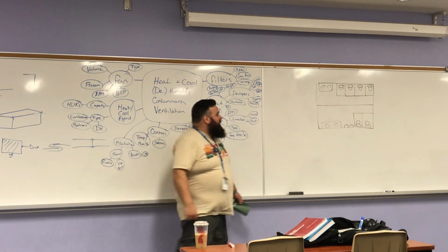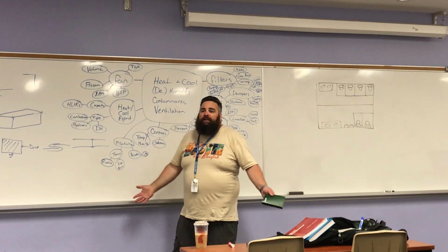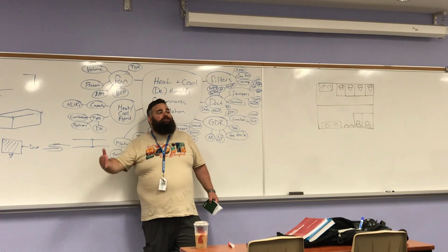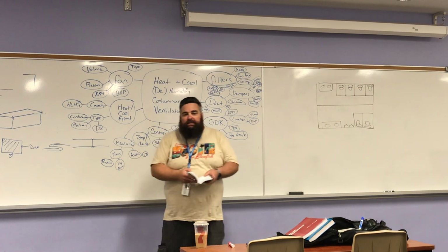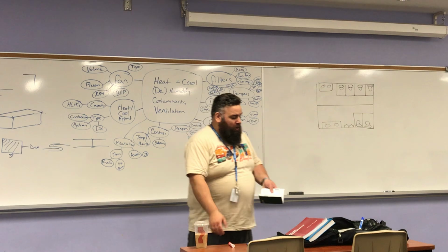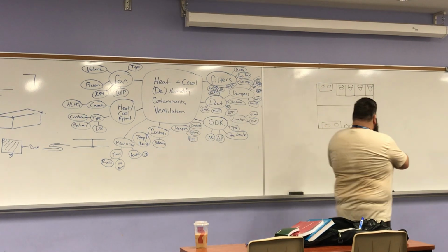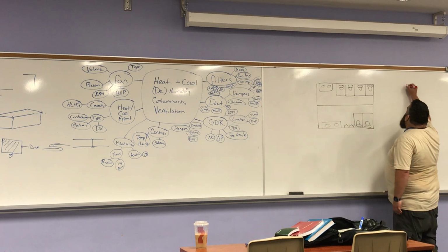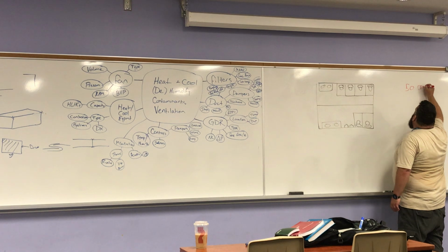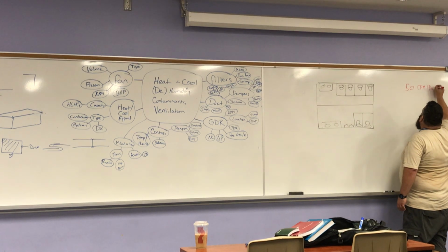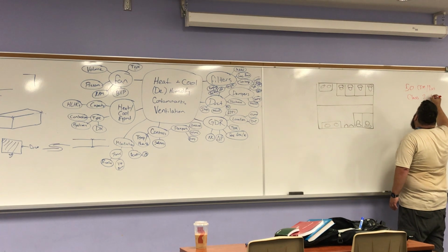Now let's just say this is an office, and we're just going to see regular use throughout the day. We're allowed to use the lower rate, okay? So let's go with 50 CFM per fixture, okay? So I'm going to put this here, 50 CFM per fixture, class 2 air.